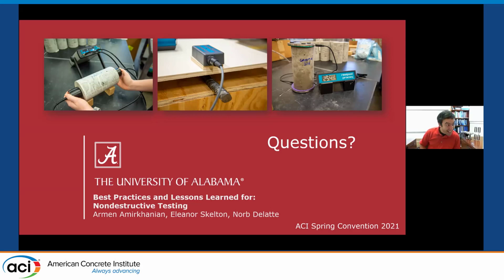All right. Hey, Chuck. So I have done cover meter on a reinforced concrete floor with them having no knowledge. I have the advantage that I have a portable GPR unit, so I could confirm the rebar location and size separate from the cover meter. Because what you'll find in especially floors, at least our floors, you'll pick up all the tie bars, the metal ties that connect the bars together.